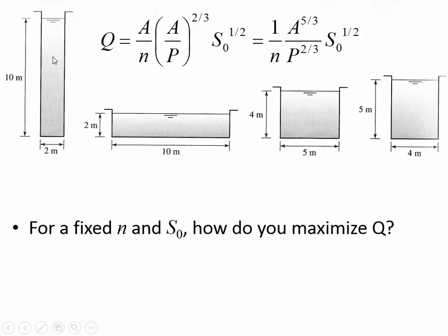And in both cases, the flow is under the influence of this roughness element that is applying a shear stress. Whereas, compare it to here, even though it is under the influence of the bottom, it's far away from the edges. And that's what's accounted for by the ratio of the area to the wetted perimeter. When you minimize the wetted perimeter, you're saying that you get more flow by minimizing contact with the location where shear stress is applied.